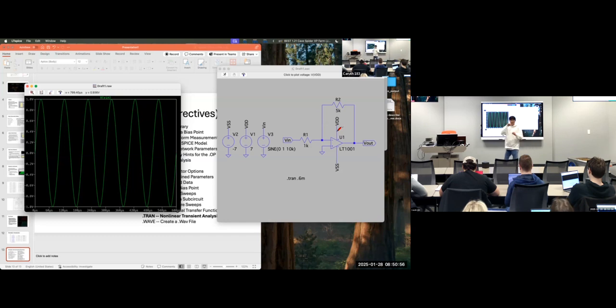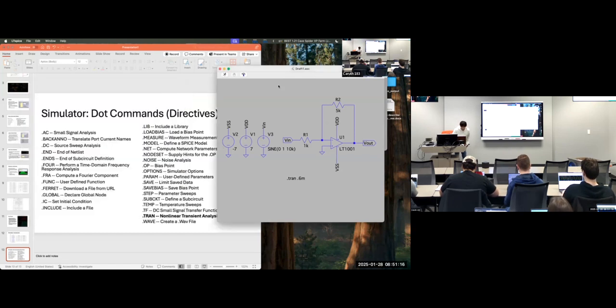So whenever you hover over a component, that's going to show its current. If you want to show the voltage, you probe it. But as y'all know, if you want to measure the voltage of something, it's not just at one point, it's usually at two points. So let's say I wanted to see the voltage across R1. What I would do graphically is click on the graph, actually I'm going to pull up a new graph real quick.